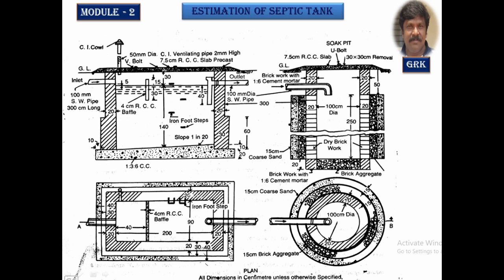This is the footing, the two short walls of the first step, two short walls of the second step, a stoneware pipe connecting from the latrine to the septic tank, another outlet pipe from the septic tank to the soak pit, a T-joint bend provided here to carry the effluent that comes from the septic tank into the soak pit, a bend, and here you find the baffle wall,